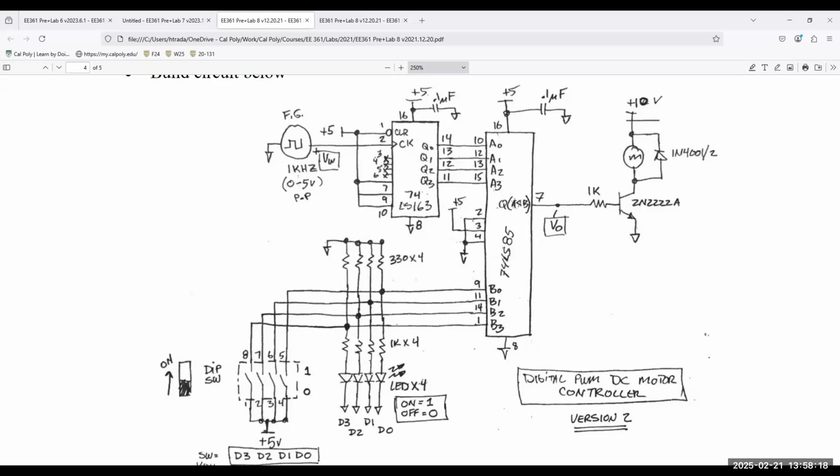That's the width of the pulse. If you increase or decrease the width of the pulse, it's said that you're modulating the pulse width. Hence the name of the technique, pulse width modulation. And you can use pulse width modulation, PWM, to turn on or turn off the transistor.